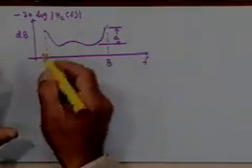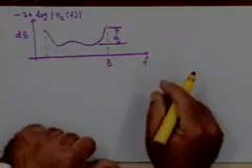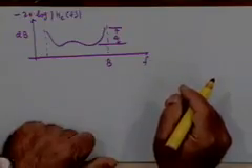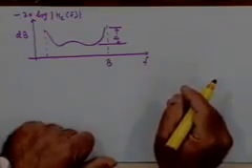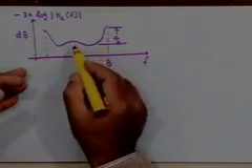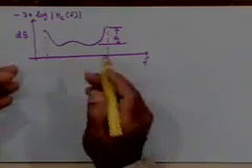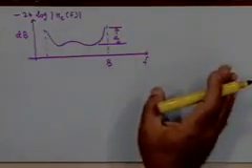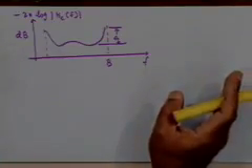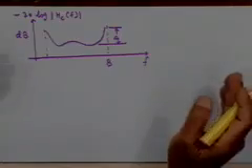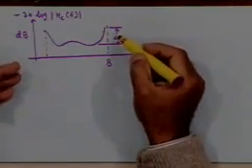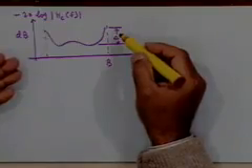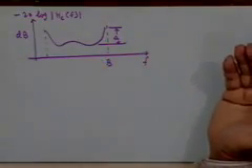I am plotting here only for positive frequencies, you can replicate for the negative frequency axis, okay. And so we are going to see characteristics like this which are not flat, right, which is what you would ideally like to see. As long as this delta is small, overall variation is small, you can ignore it, it does not matter very much, right. What is the extent to which you can tolerate it? When this variation is within a dB or so, within 1 decibel or so, that is a rule of thumb for you to remember, right.